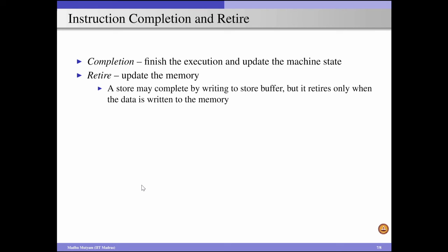As a result, whenever there is contention for the memory between loads and stores, we have to give priority to loads so that the processor will not be stalled for the load value, and it can improve the overall performance. Since we are giving importance to the load instructions when a load and a store instruction are contending for the memory, the store instruction will write to the store buffer, and from the architecture point of view we can say that the store is completed, but the actual data will be written to the memory only in the retirement stage.